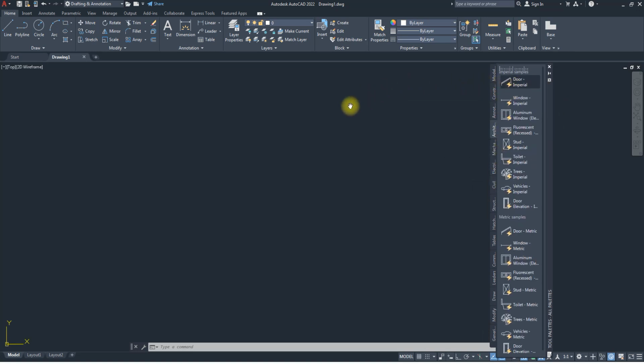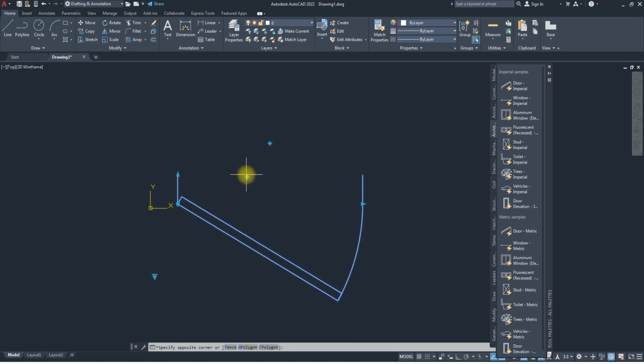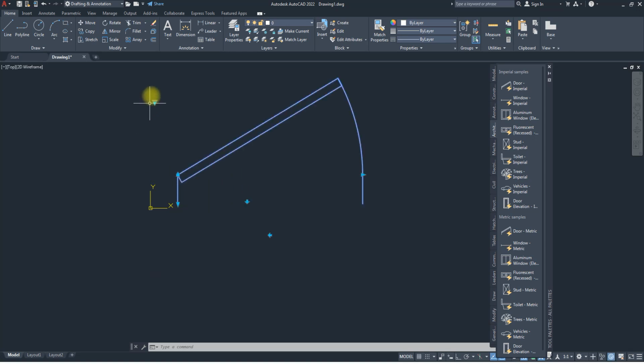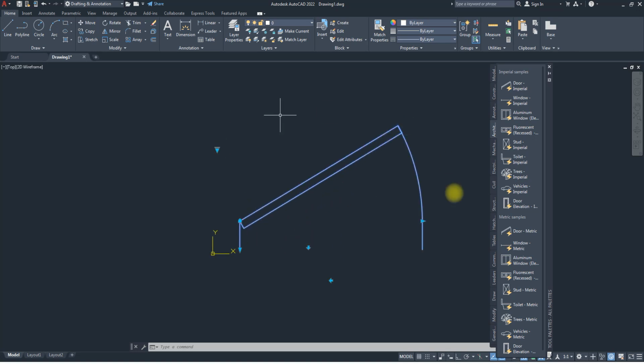You notice if we bring in a door, you have this. And this door, if you remember, if I select it, we can flip it. And we said we can use this one to change the different visibility states. Maybe we want it 90 degrees open, and you notice all these things are changing. It's because it's a dynamic block effect.